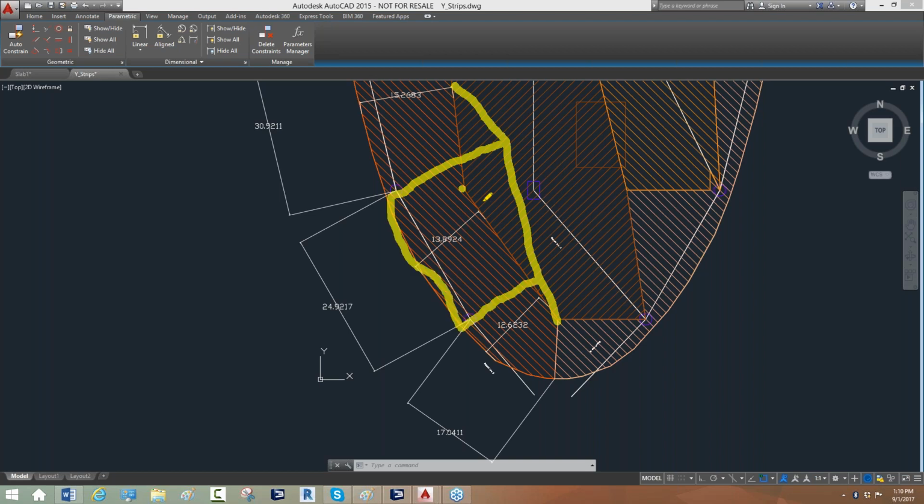And that panel is shaped like a trapezoid. We have greater tributary as we move from bottom to top. So rather than just modeling the entire panel, the greatest length or the greatest tributary width, we might break that up into segments. 1, 2, let's say 4 segments here.